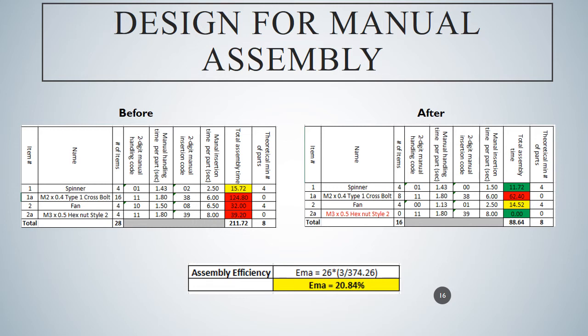As you can see, there were 3 redesign choices made in order to help reduce manual assembly time. One of them was the reduction of fasteners, going from 4 to 2, which will help reduce assembly time while retaining functionality. Another was a fillet inserted on the top of the shaft to help with insertion. The last was a snap fitting receiver in place of the previous threads to help receive the propeller snap fitting.